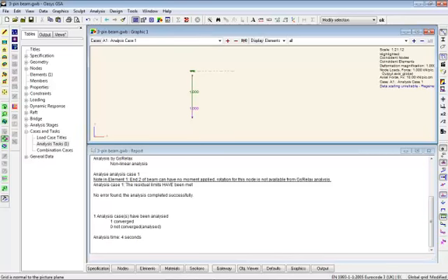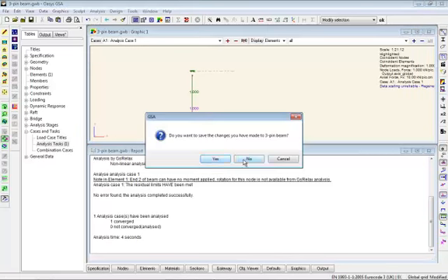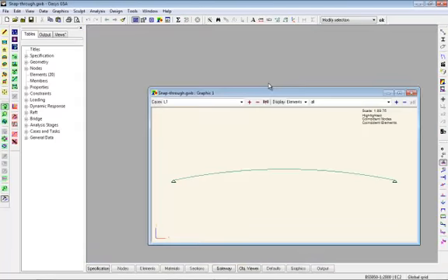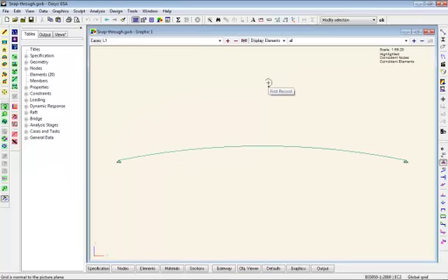Another example of these geometric non-linearities is what we call the snap-through calculation. Now, the snap-through, and this is an arch, but likewise could be a portal frame. We have an asymmetric load on this structure, and we can increment the loading until the structure fails, so it snaps through, and rather than being an arch, becomes a catenary.